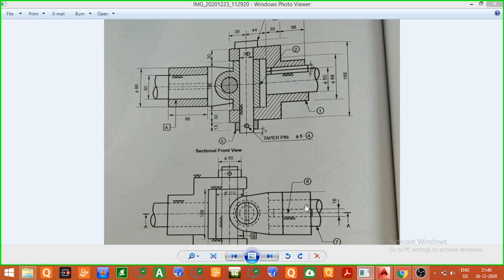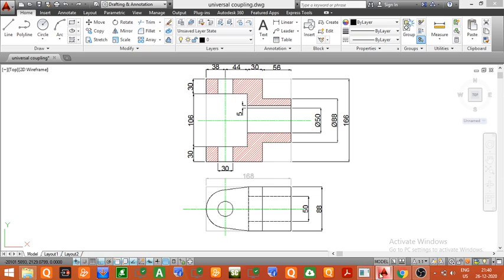So what is the width of the hole? You can see the width of the hole is 16 mm. So from the center line you have to draw a hidden line of 8 mm on the upper side and 8 mm on the lower side. So now we will draw the top view of this slot which is used for inserting the key. Now the slot again begins from this point or this end and it ends here. So we have to represent the keyhole from this line up till this line, that is from here to here, with width 16 mm.